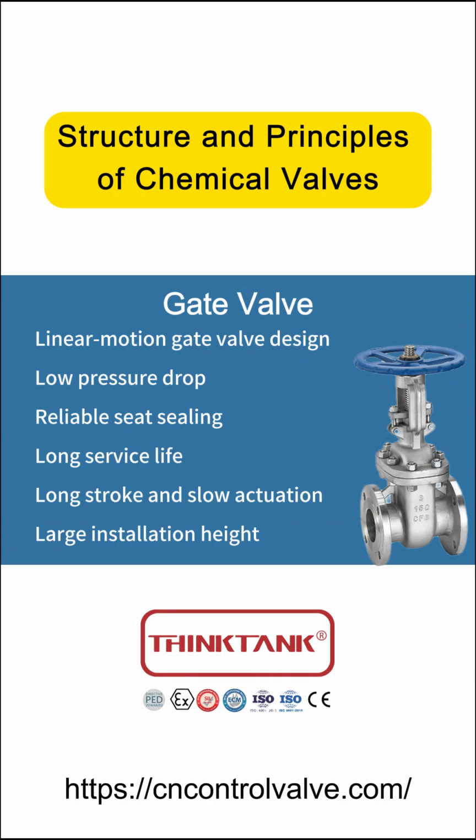The gate valve has a simple structure. The media does not change its direction of flow when passing through, resulting in low fluid resistance. It is easy to operate, has a wide application range, provides stable and reliable sealing, and is durable. However, it has a long travel, a long opening and closing time, must be either fully open or fully closed, has large external dimensions, and requires a certain amount of space.